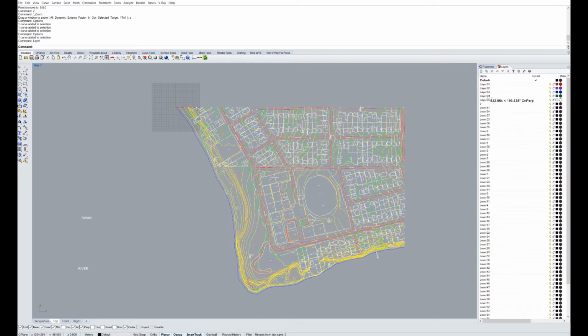In my case, I'm going to create a couple of new layers, and whenever you create a new layer, usually by clicking this button, you name them. So there's buildings, there are roads, and the way you name them is so they are descriptive. So you know what you're looking for once you've assigned things to them, once you turn them off, once you lock them. So you know what objects are on each layer. You want to make it as descriptive as you possibly can.